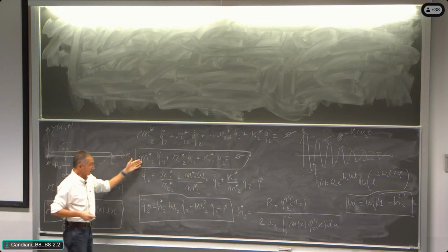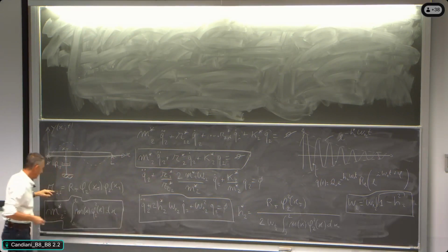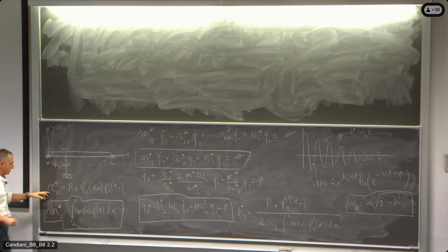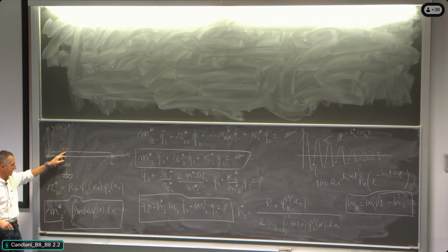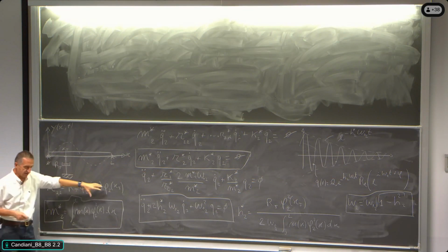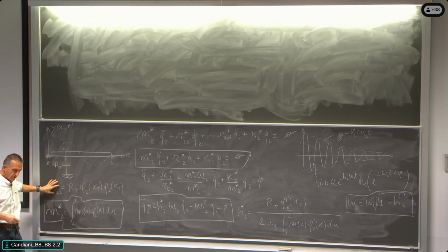So the equation is written in this way. The number R star 2 that was calculated here is written in this way. So it is the damping characteristic of the damper multiplied by the modal amplitude of mode 2 at the location xj, twice. If we are working out the equation using the dissipative function, we arrive at this quantity, all right? And so this is a known quantity, but which is the non-dimensional damping?